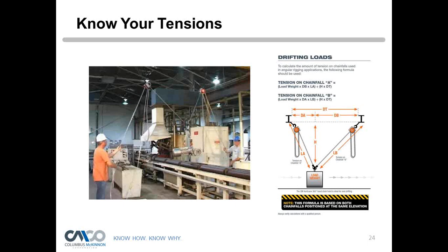You could even have somebody weld up a block of steel, then drill it out and connect a swivel hoist ring to the bottom of the I-beam. Again, you would want a qualified person to evaluate the I-beams you're connecting to, to be sure they have the strength to hold up what you want to do to it. A lot of times we see drifting loads like this when you're removing a piece of machinery from an area that is not accessible to an overhead crane or a tow motor. Usually it happens in a pit where you have to pull motors and things of that nature.